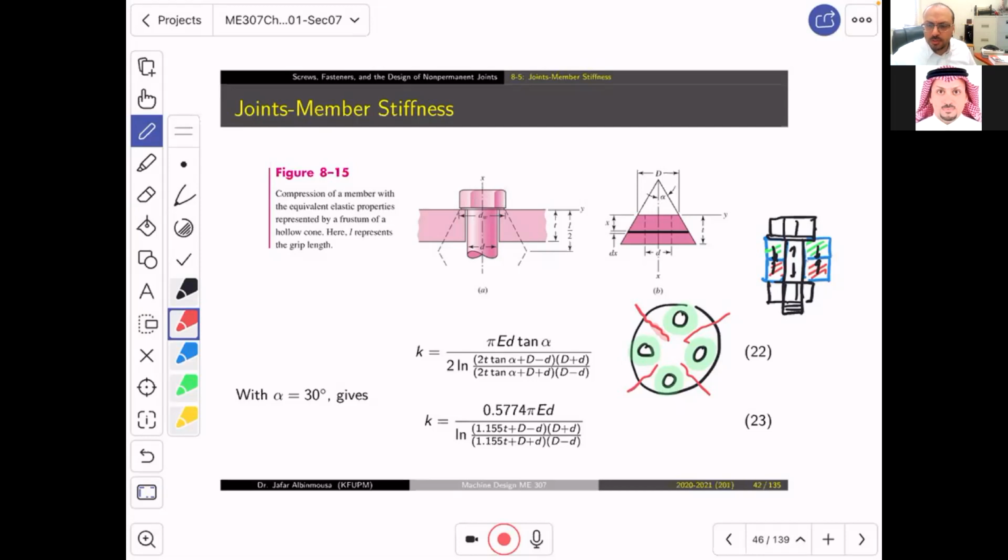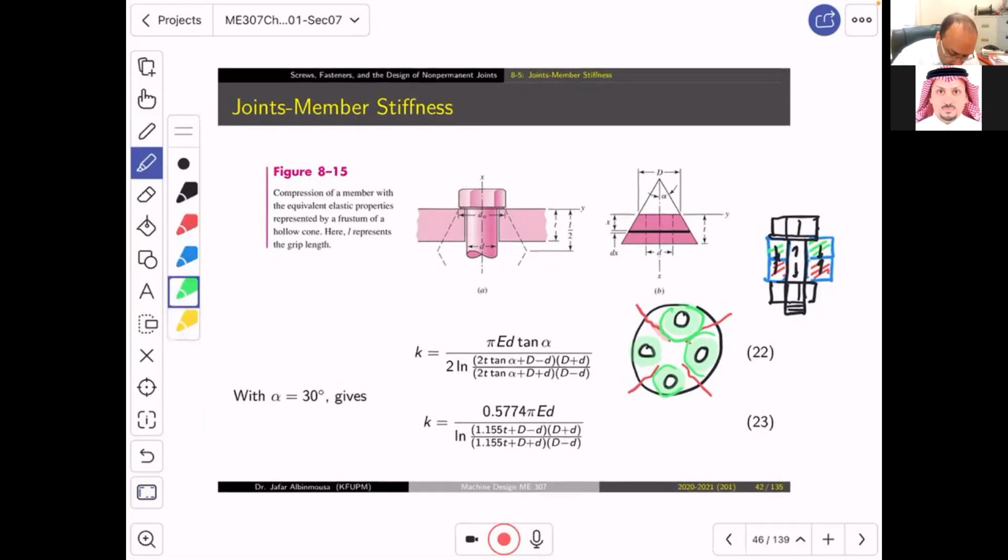What is the clamp? The thing that we put the clamping force in. You mean the bolt? Yes, the bolt, the screw. We call it a screw. A screw, guys, as you clamp more, it stretches more. It's like a tensile test. You can stretch it until one moment it will break. So what do we do? We can't just keep clamping. Although clamping might increase the green area a little bit more, the bolt will break.